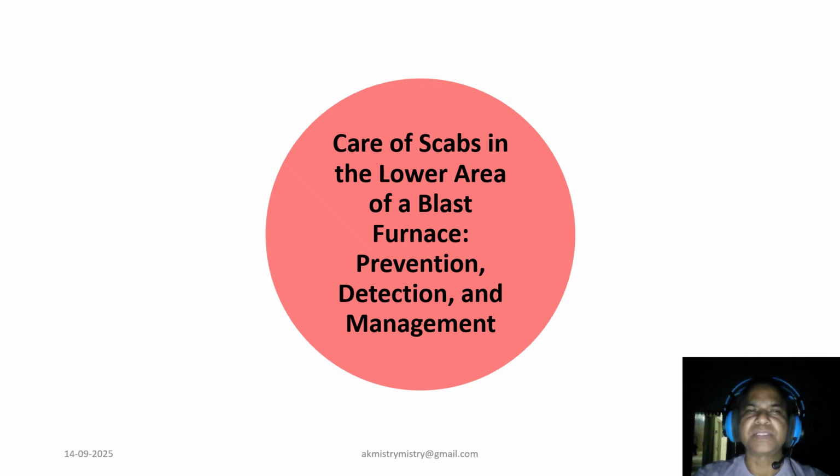Today we are addressing a crucial operational issue in blast furnace iron making, the care of scabs in the lower furnace. This unmolten material accumulation poses significant challenge to furnace stability and efficiency. We will cover their nature, causes, and how we prevent, detect, and manage them effectively.